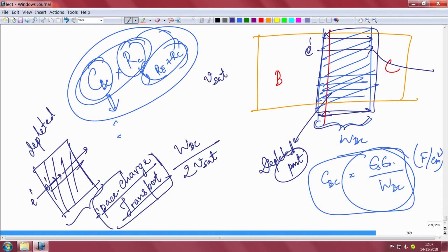So the electric field within this is defined essentially by the carriers that are moving across the film, and the background carrier concentration is very low, so it's almost depleted. In organic semiconductors or insulators, for example, which have very low background concentration like a dielectric, the transport typically is space charge transport, because the carriers that you are injecting will define the field inside. So in space charge transport, the time taken will not be the distance by velocity, but distance by 2 times the velocity, or half the distance by velocity. So now we know the various terms that are associated with the delay.